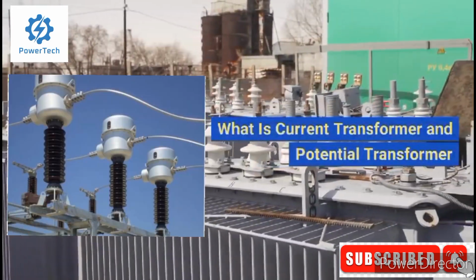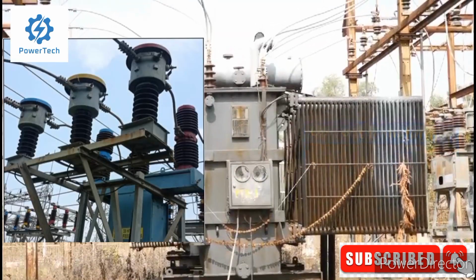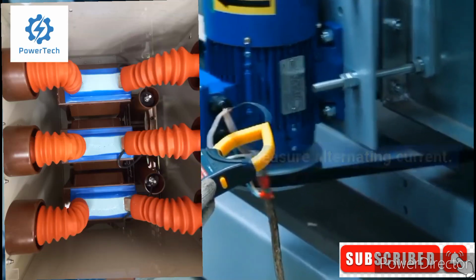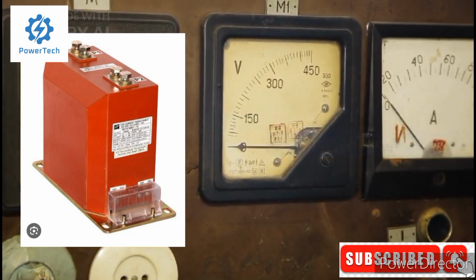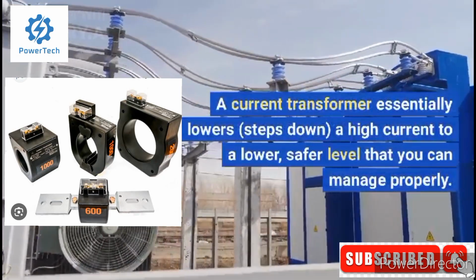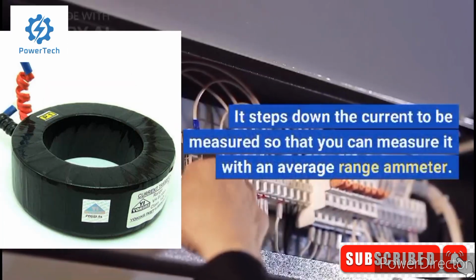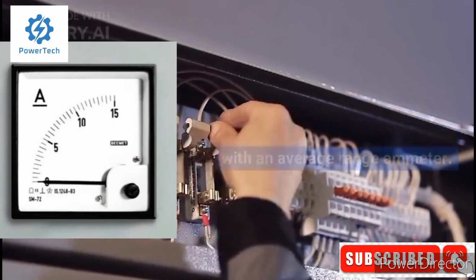What is current transformer and potential transformer? Current transformers, also known as CTs, are devices that measure alternating current. They are widely used to measure high-magnitude currents. A current transformer essentially lowers, steps down, a high current to a lower, safer level that you can manage properly. It steps down the current to be measured so that you can measure it with an average range ammeter.